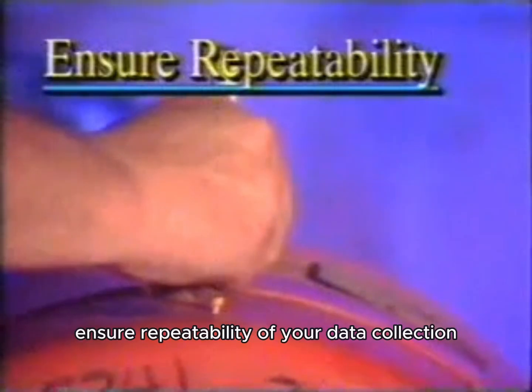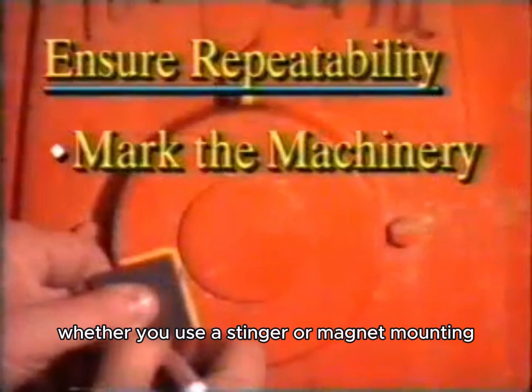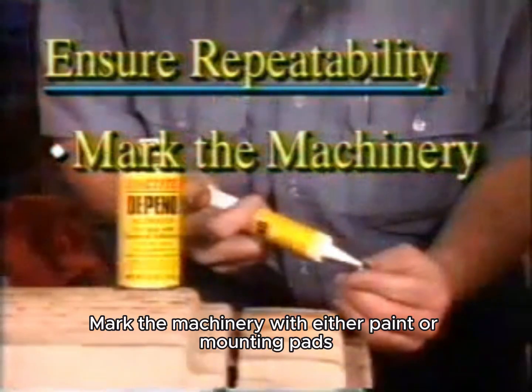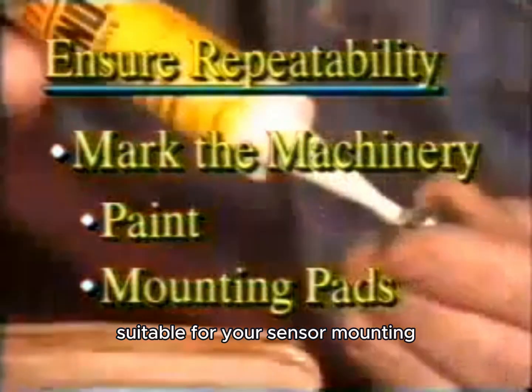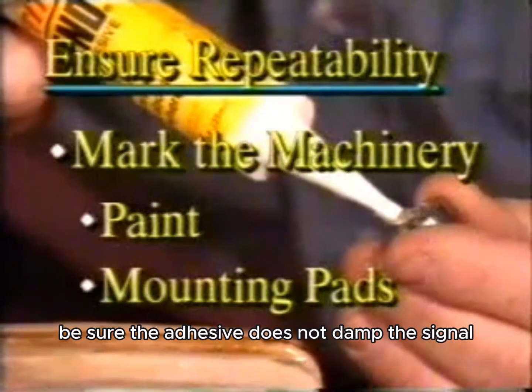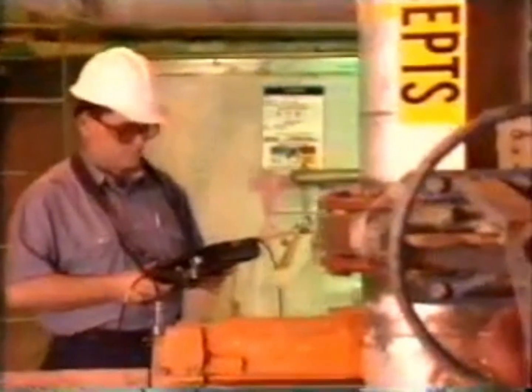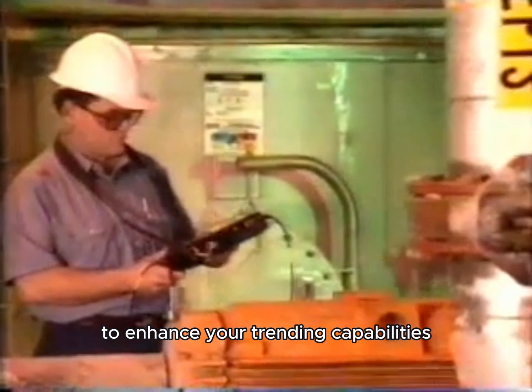Ensure repeatability of your data collection by marking the machinery. Whether you use a stinger or magnet mounting, mark the machinery with either paint or mounting pads suitable for your sensor mounting. When using the mounting pads, be sure the adhesive does not damp the signal. Routinely measure these same locations to enhance your trending capabilities.